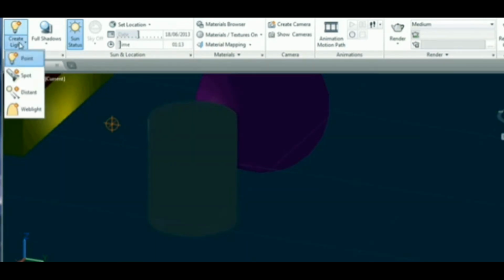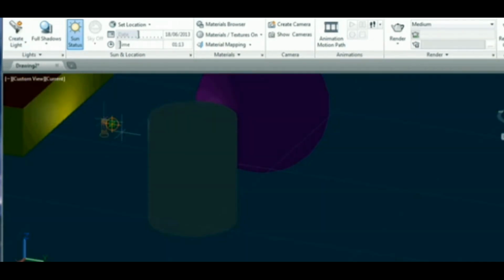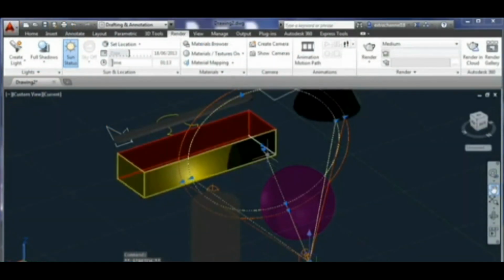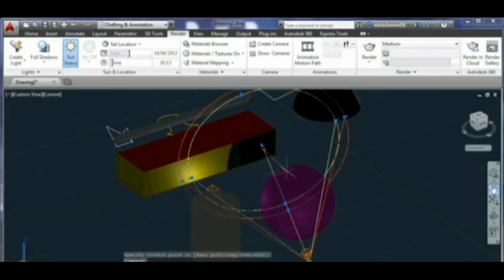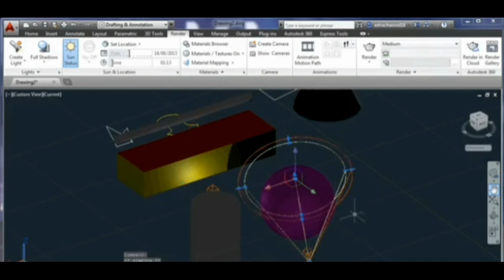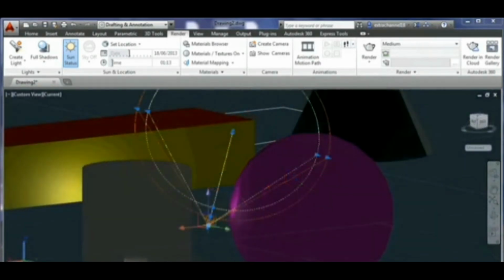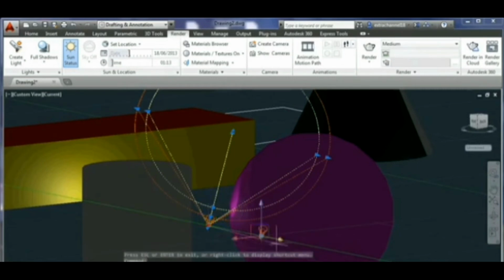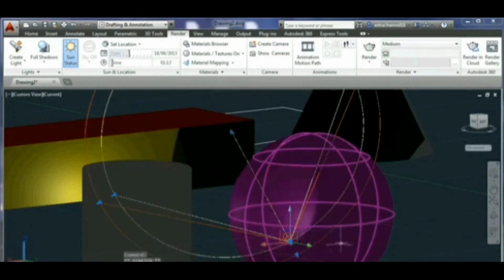The spotlight is a directed light, indicated with a torch. Firstly a placement is made, which is always made on the XY space. Then you set its direction. Then just type X and enter to finish. The direction of the spotlight is its target that you can edit through the central point of its cone's base, and such stays fixed whenever you move the spotlight later.